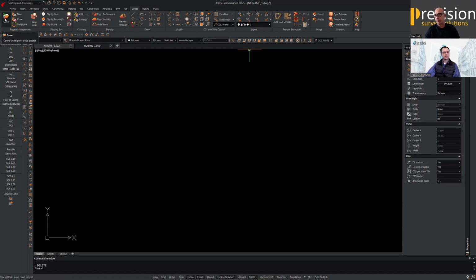So you can either open a project that you've indexed already. Just like AutoCAD or Autodesk products, Autodesk uses the RCP and RCS solution. So any third-party or native file formats, such as the laser scan FLS files from Faro, the Leica format files, E57s or LAS, any of those types of large point cloud data gets indexed.